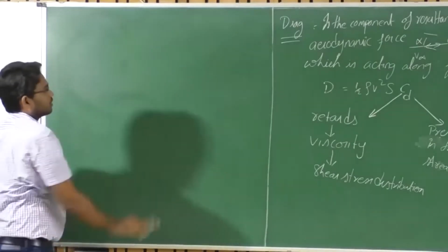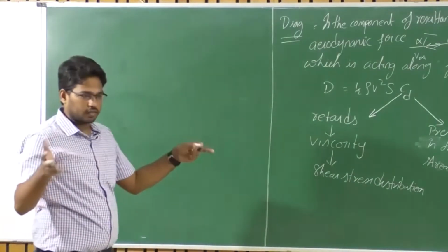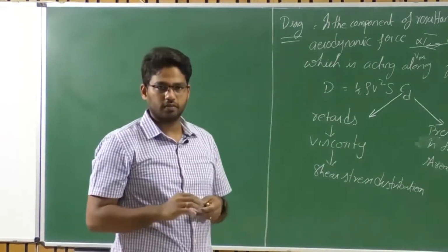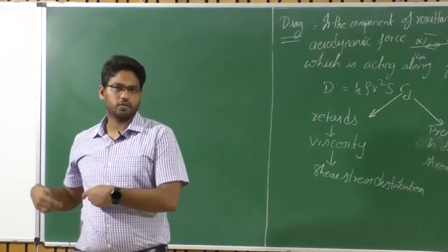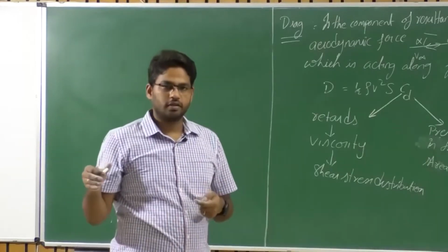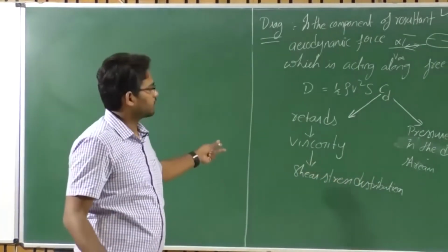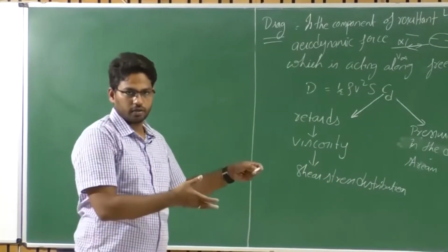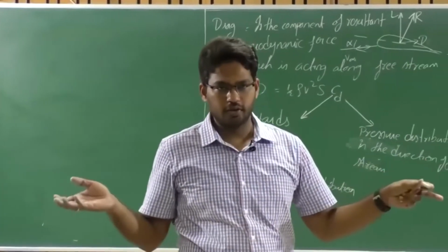Do you remember? We talked about lifting line theory, where there is a horseshoe vortex with a bound vortex and then two associated trailing vortices closed by a starting vortex, right? It characterized high aspect ratio wings in terms of their lift curve slope. Right? So we can use that theory to characterize those high aspect ratio wings.